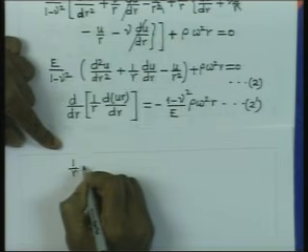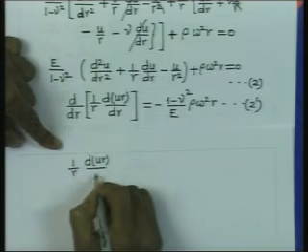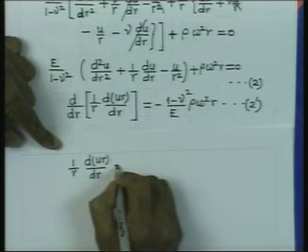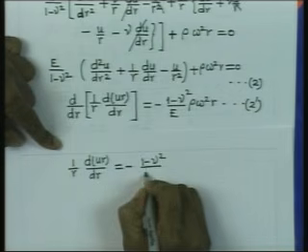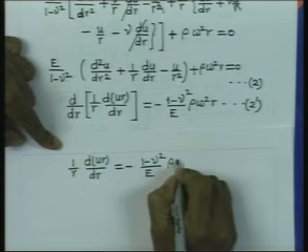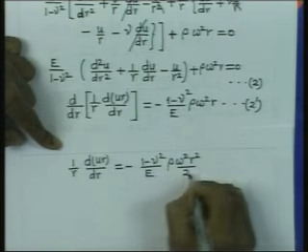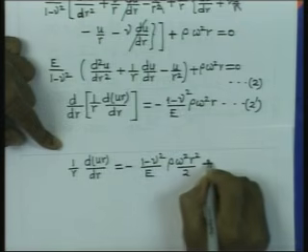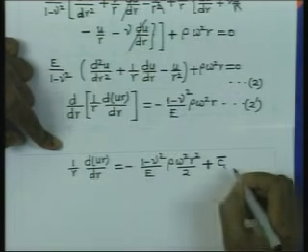1 by r d(ur) dr is equal to minus 1 minus nu square by E rho omega square r square by 2. Let us write this constant as C1 bar, where C1 bar is a constant.